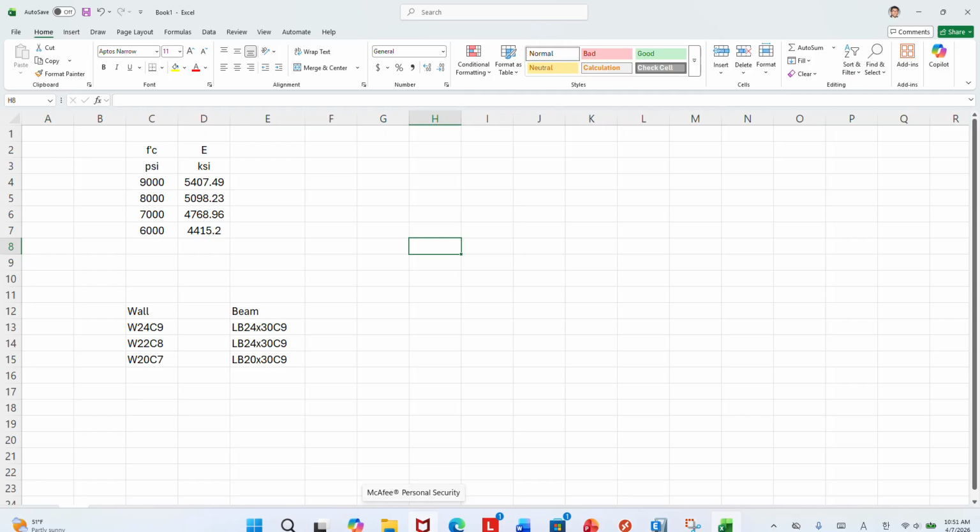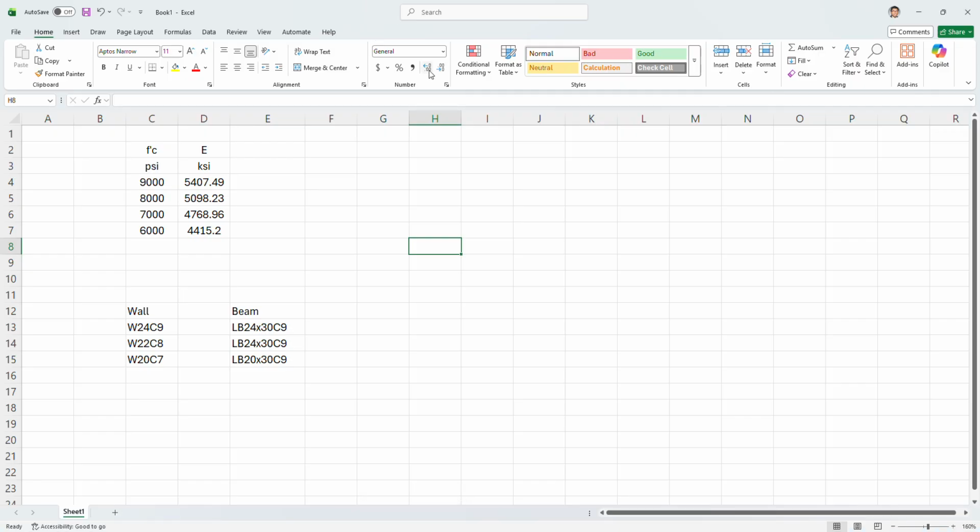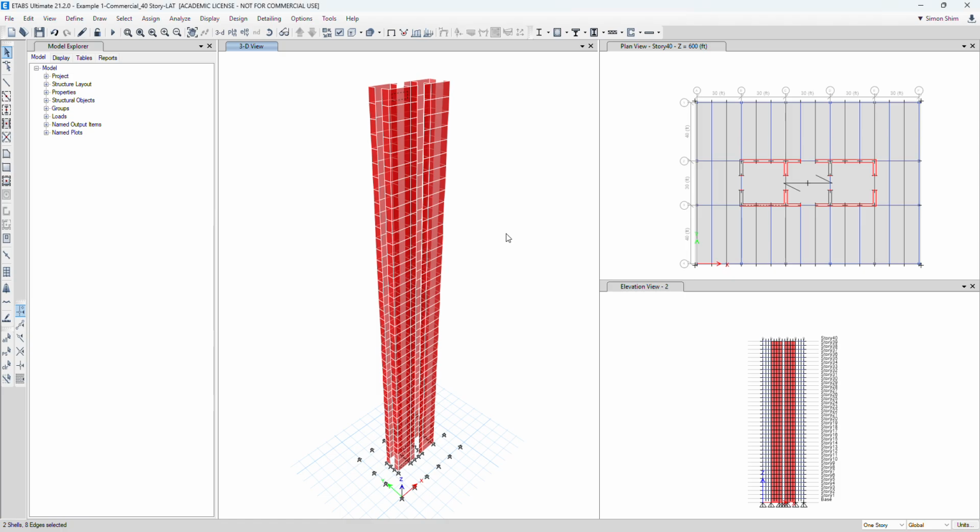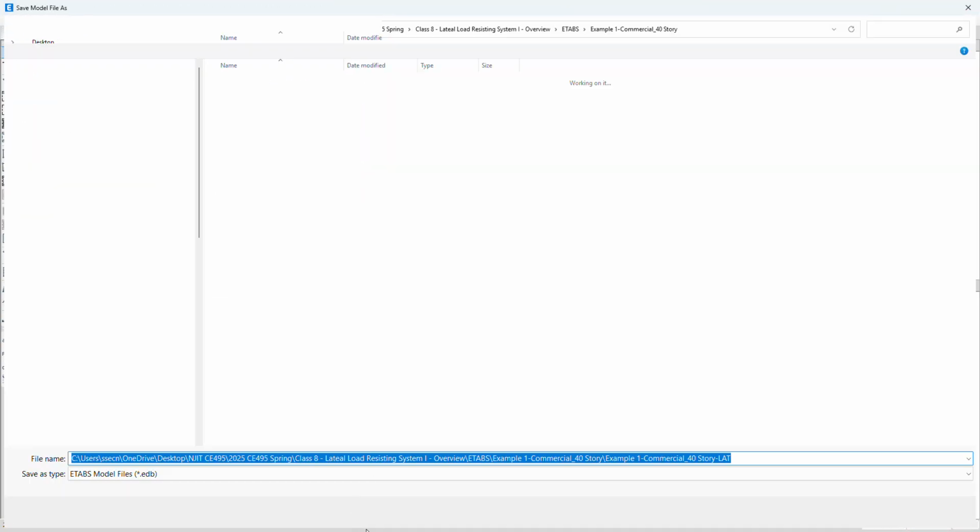Okay, the current building core wall layout, wall thickness, and concrete strength. So we run the model. Based upon the service wind load, what is your deflection? Now, since we know that, we're just going to start scaling up the wall and concrete strength. We're going to do a few iterations to find out how to meet the criteria. So let's open ETABS. So this is the model. You save it as a different name. This is your scaling up model.